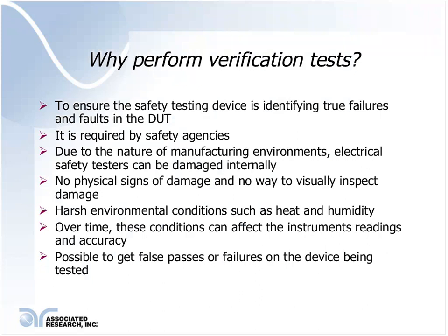And due to the nature of manufacturing environments where these electrical safety testers are being utilized, they can get damaged internally without showing any physical signs of a problem. As a result, these damaged units can give incorrect readings with regards to insulation resistance, leakage currents, and withstand potential. Therefore, performing regular verifications on electrical safety testing equipment ensures proper operation and testing to agency standards.